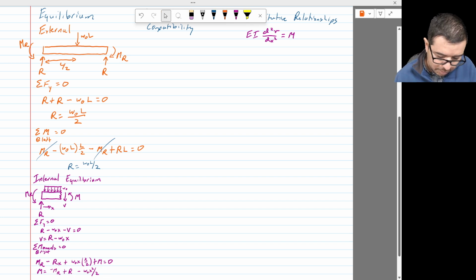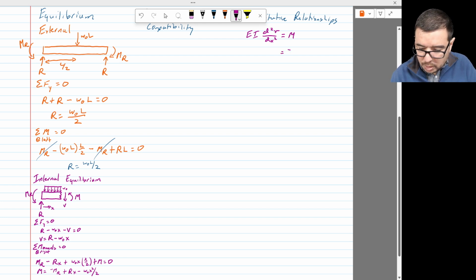And maybe I should not have R sub x. No, it's just R times x. But we do know what R is. And so let's just go ahead and do a substitution. This is going to be minus MR. Okay, R is W naught L over 2, so that's going to be W naught L over 2 times x. And we have minus W naught x squared over 2. Just like that.